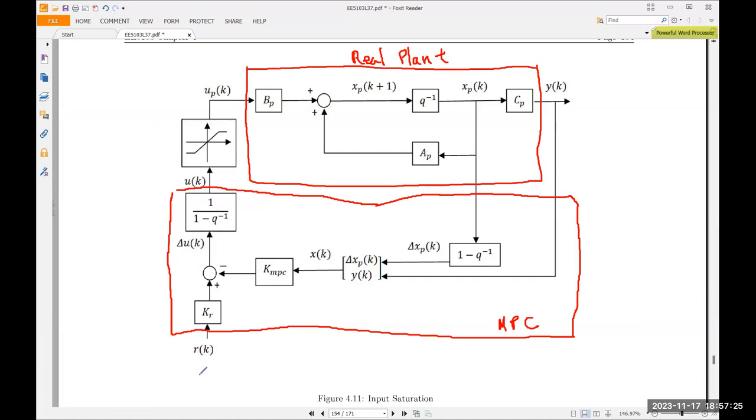So in this question, just to make the number easy, I put an upper constraint here as 0.2. So MPC can calculate anything. It can calculate 0.5, but 0.2 is a real constraint. So the amount of chemical flowing into the plant is restricted to 0.2, even though you output and say, hey, send in 0.5. All right, or the power or the voltage.